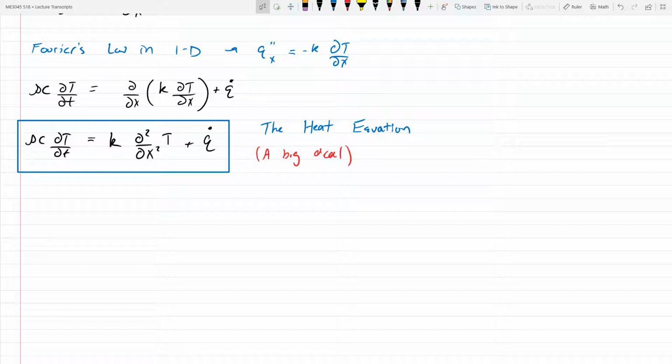So what law of thermo is this expressing? Well, it's actually both, right? We have Fourier's law, which is essentially an embodiment of the second law of thermo, saying that heat transfer has to occur in a direction of decreasing temperature. That's where that q heat flux comes from. But the entire thing is just a reworked version of conservation of energy. It's just the first law with some substitutions made in, for a small volume.